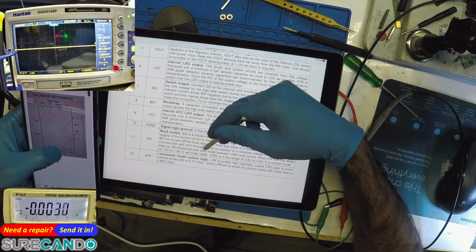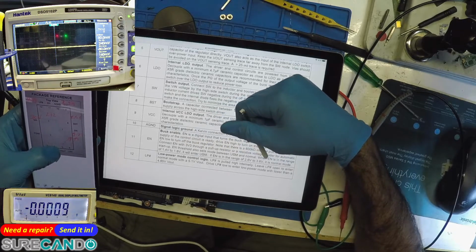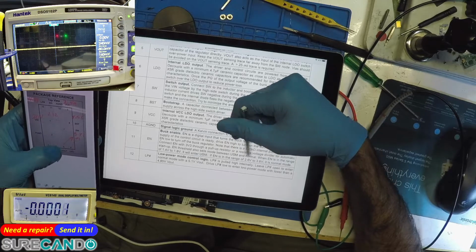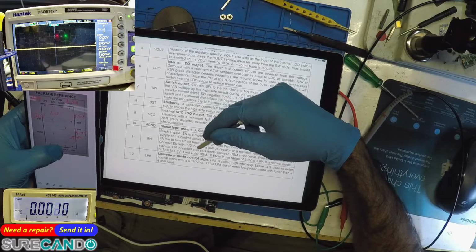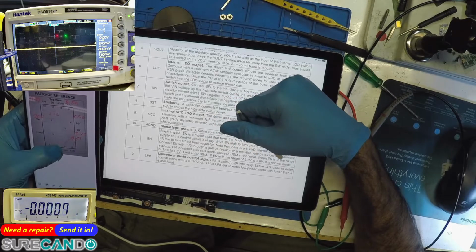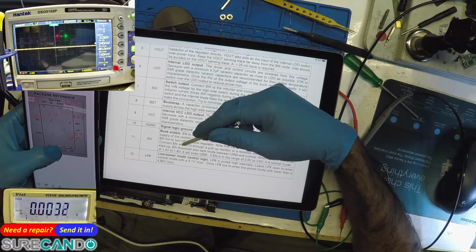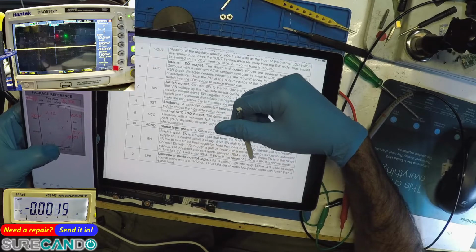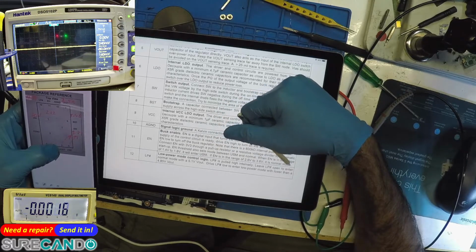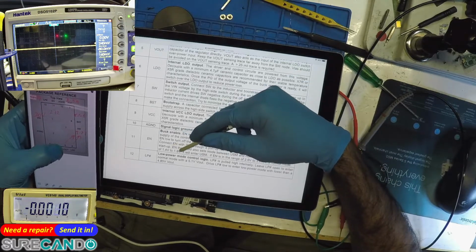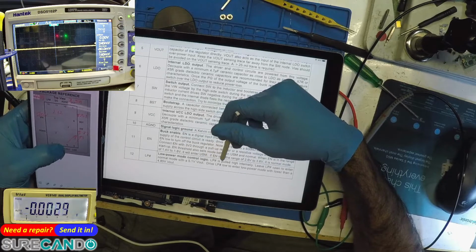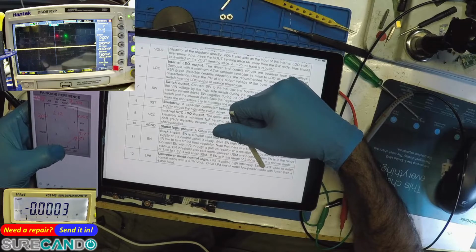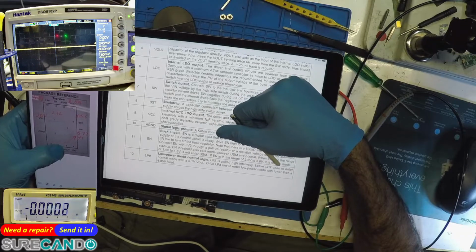Connect EN to a 3.3V pull up resistor or resistive voltage divider for automatic startup. EN threshold also sets the mode between USM and normal. When EN is in the range of 1.4 to 1.8, it will enter USM. If EN is in the range of 2.6 to 3.6, it's normal mode.